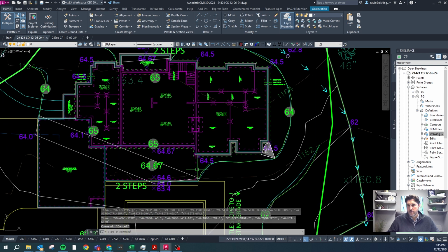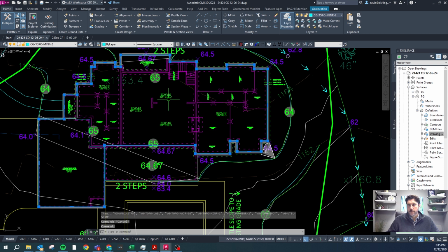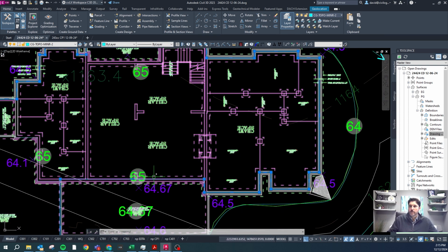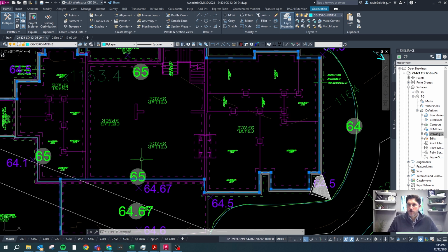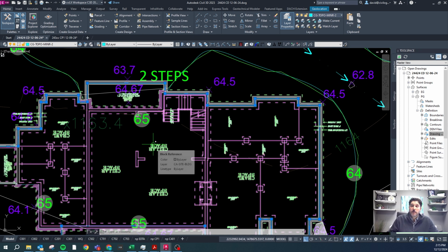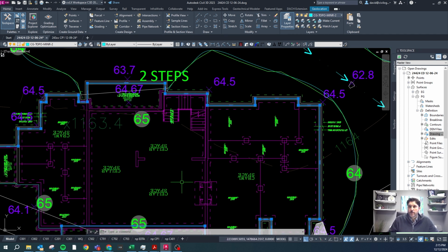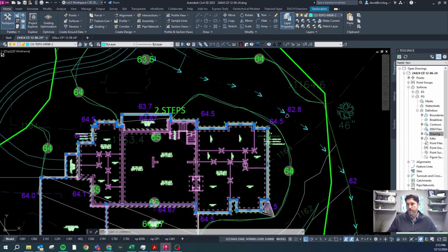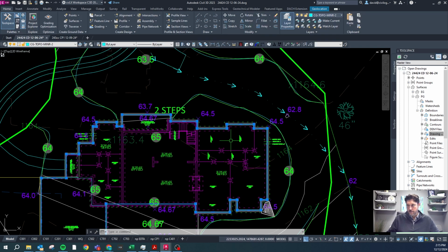And then this boundary around the house is going to be, the house is 65. They're doing a crawl space, so it's going to be probably at least a foot down for the floor joist system, then 2 feet of space, so that's 3 feet, so it should be at least 62. Maybe it should be a little bit lower than that. Maybe we'll do 61, 1161.